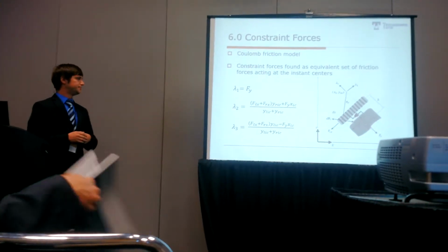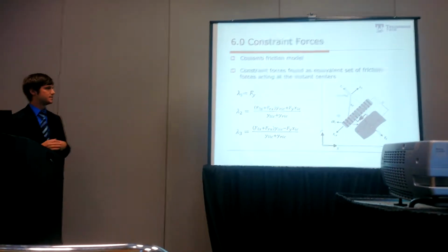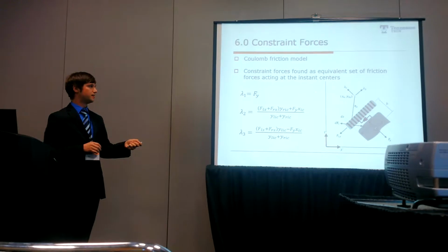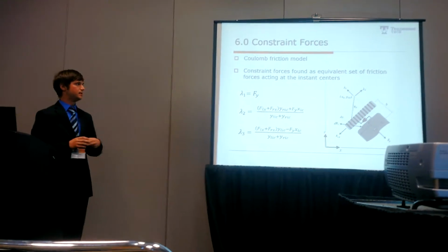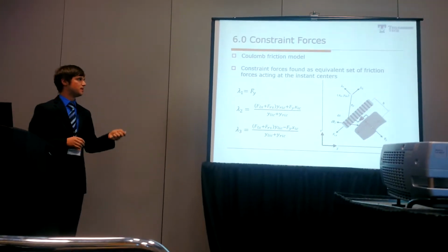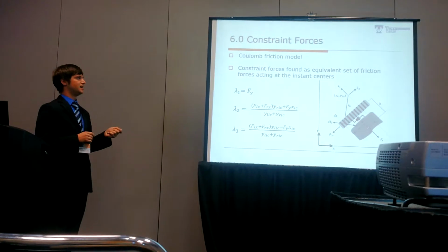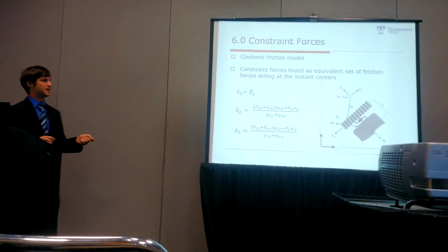Constraint. Here are our constraint equations, and we see that they are a function of force and instant center locations. On the right here, this schematic is just showing where these constraints are acting, and once again, they're acting at the instant center. So I'd like to emphasize that these are the constraint forces found as an equivalent set of friction forces acting at these instant centers.